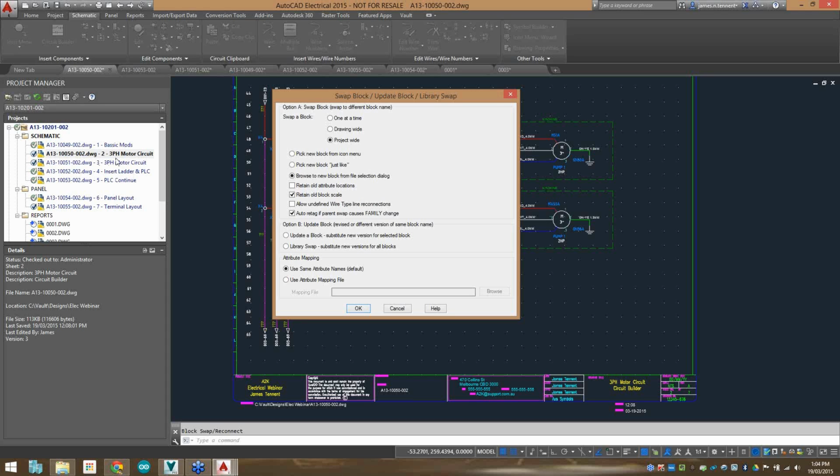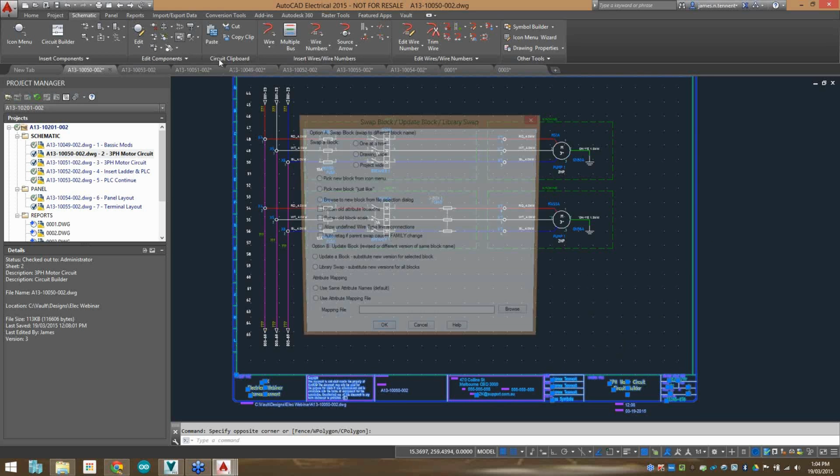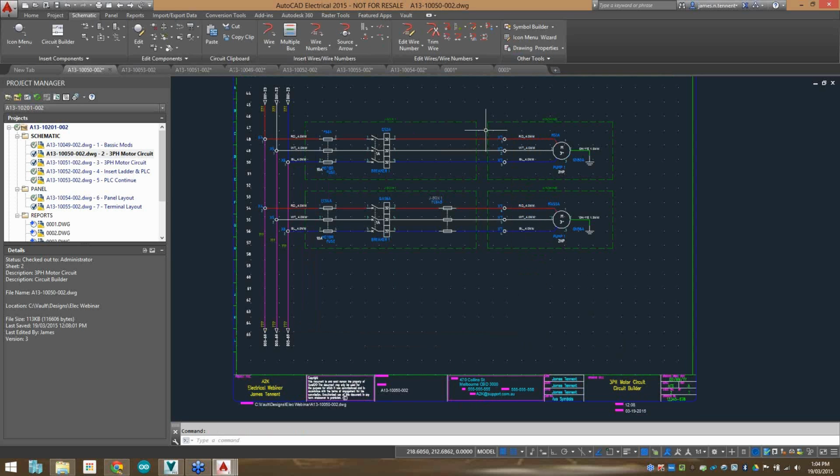So there is a tiny little mapping attribute inside of the template, and that mapping attribute tells you how to map from, for example, a drawing description line into the title block itself. So there's a couple of little things we need to do, but the answer is yes, we definitely can do it, and it is some variation of using the update swap block, but I haven't done it in a couple of years, so you might just want to have a play with that. Yeah, so that's definitely how to do it.